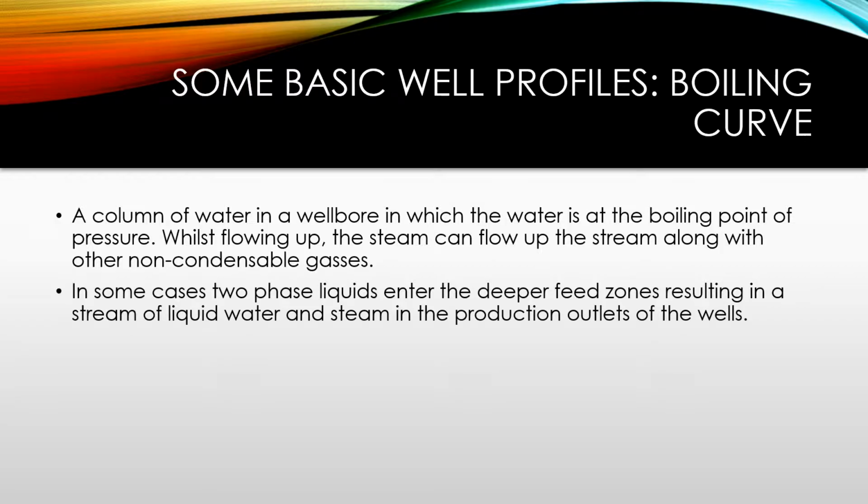Boiling curves. A column of water in a wellbore in which the water is at boiling point for pressure. Whilst flowing up, the steam can flow up along with the other non-condensable gases. Now, here is where we start to see why it's important to know about the content of non-condensable gases. In some cases, two-phase liquids enter the deeper feed zones, resulting in a stream of liquid water and steam in the production outlets of the wells.